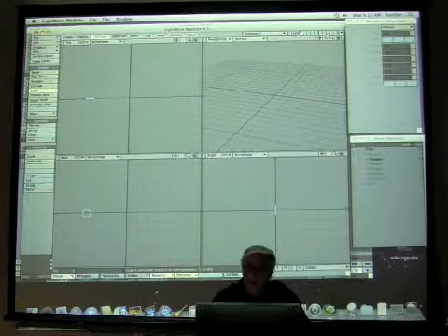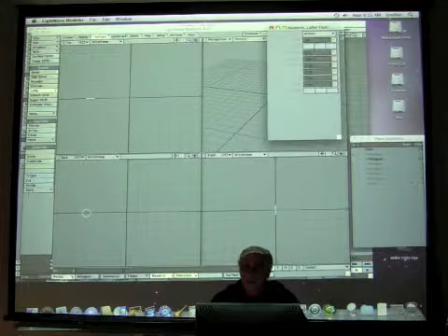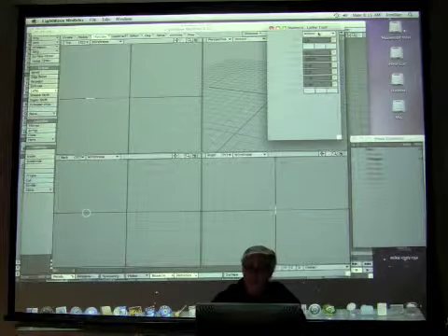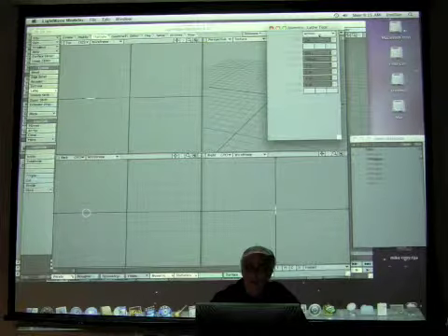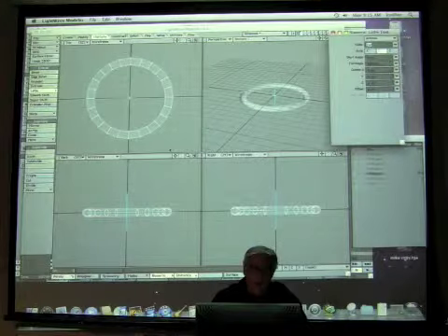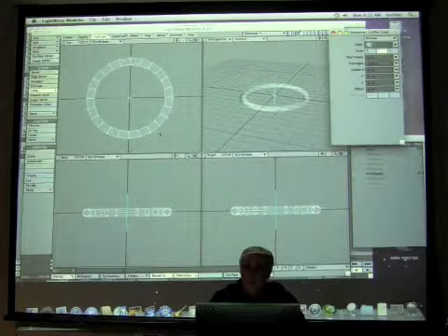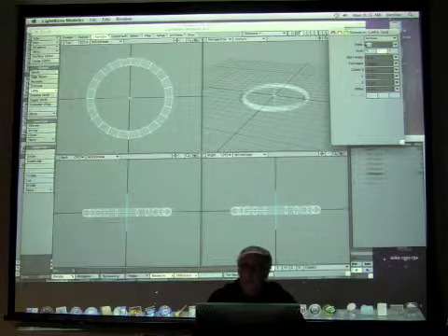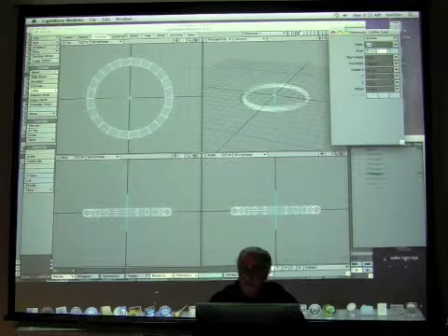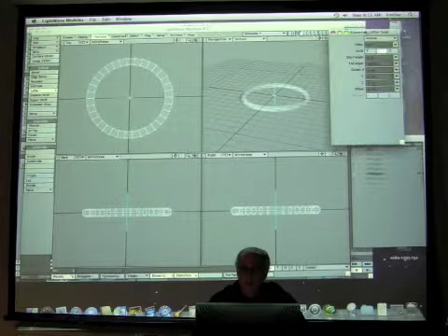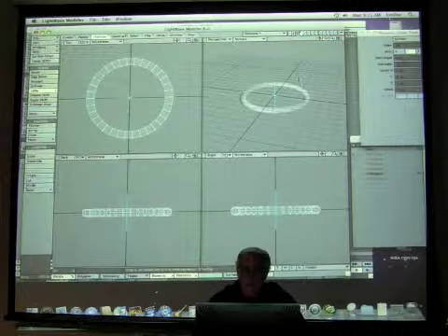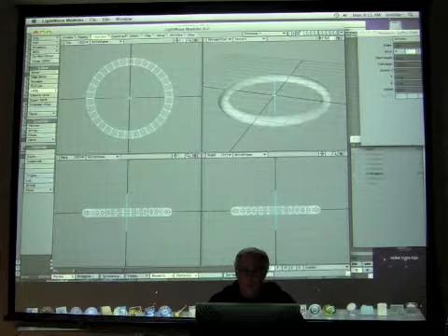And by selecting that now, or you can come over to Actions, and you have to have actions really to effectively use this visibly. I'm going to go ahead and reset, and I'm going to go ahead and activate, and when I do, notice what it does. It takes from the center point and it spins it around. And you'll notice by default, it has 24 sides. Remember, you can click in there and add sides, or you can use the spinner to the right and you can add. Now, something I did wrong, and it's not a big deal, but does this donut shape in perspective view look a little bizarre to you at all?